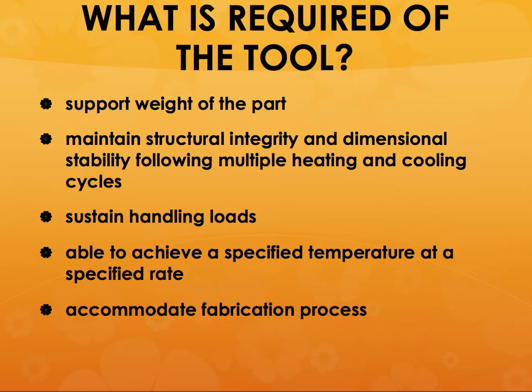So what is required of the tool? It has to support the weight of the part. It has to maintain its structural integrity and dimensional stability. Suppose you are making hundreds and hundreds of parts. This tooling should not get damaged during the process, and you need to be able to sustain its handling loads.